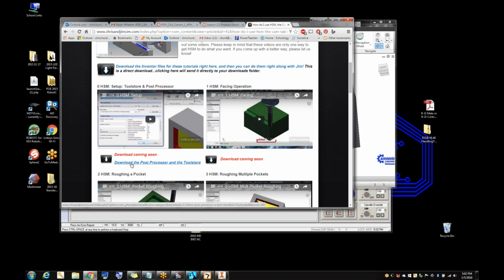So you mentioned earlier you had like a 3x3 block, and you make them keep their design inside a smaller area. Does that have to be a 1/2 inch from the edge then, since you're using a 1/2 inch? No. I use an 1/8 of an inch offset. So that really means I'm losing a 1/4 of an inch worth of my stock.